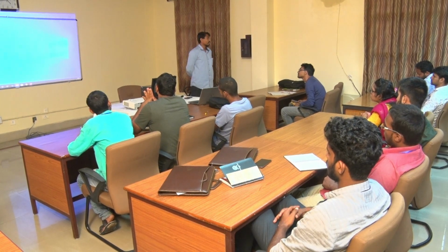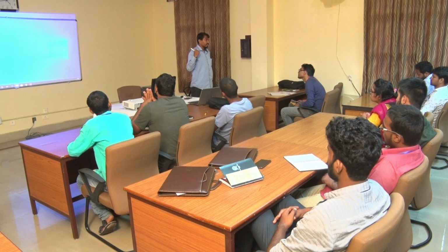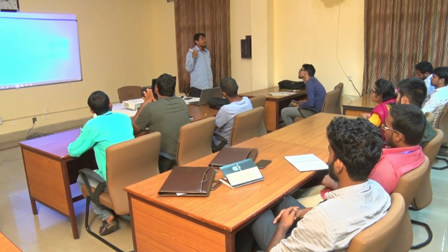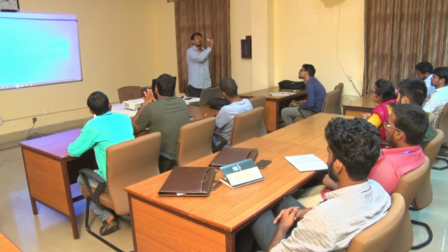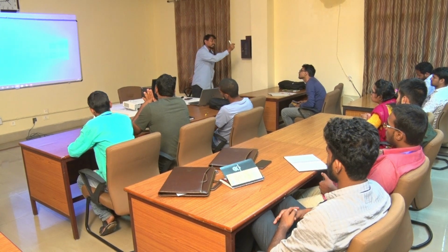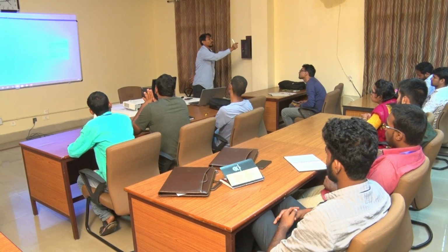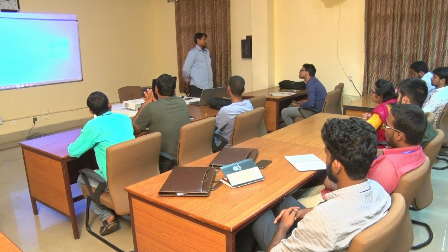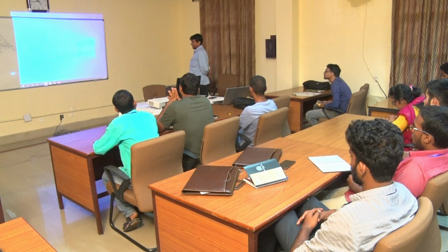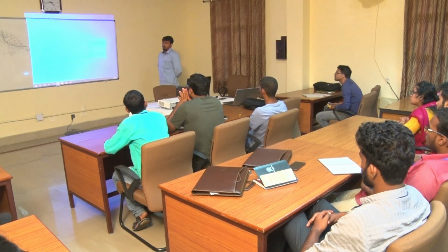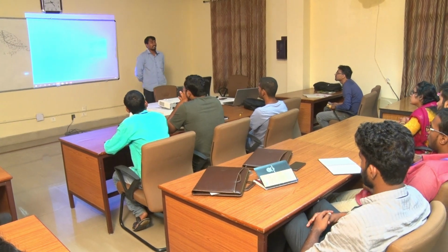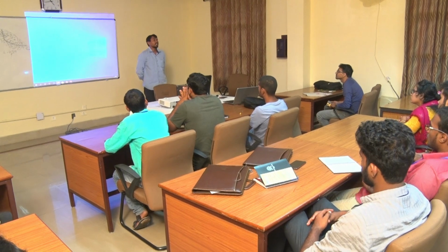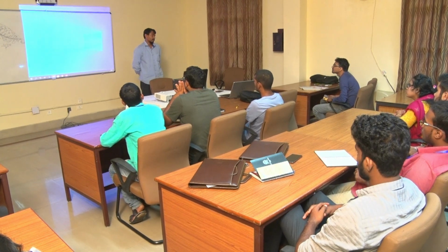Even though the material is heterogeneous, what we are determining in the lab for characterizing this kind of rock mass is the homogeneous sample of small fine soil only. Because from the dynamics of the movement of the slope mass, it is observed that failure is generally through the loose and weak zone only.